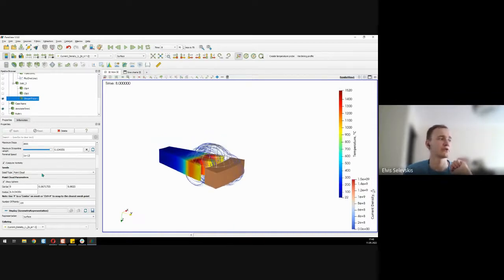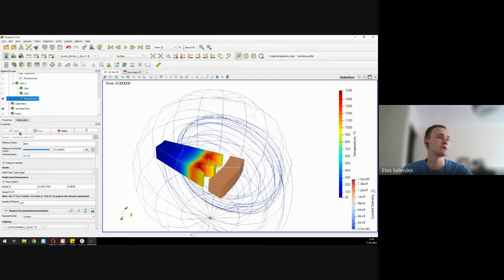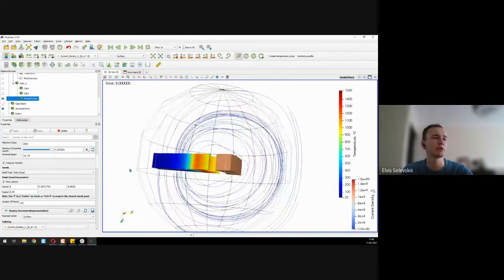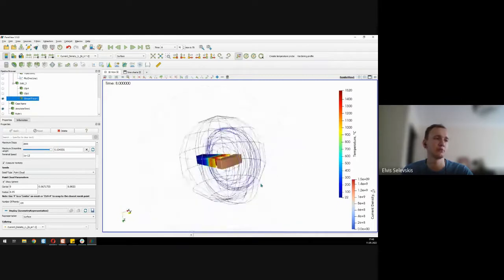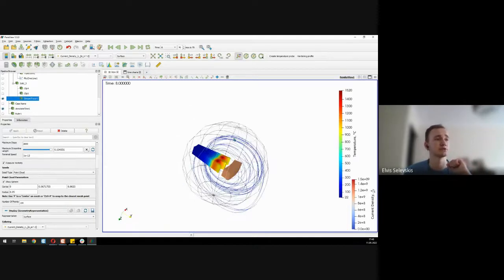For this point cloud, you can see that it's quite small in this case. So what we can change, where we have the radius, is the size of it. If the radius is 0.013, I will increase it to 0.05. That's roughly 3 times. Press apply, and we can see that the point cloud is a lot larger, and the magnetic field lines have also developed to be longer.